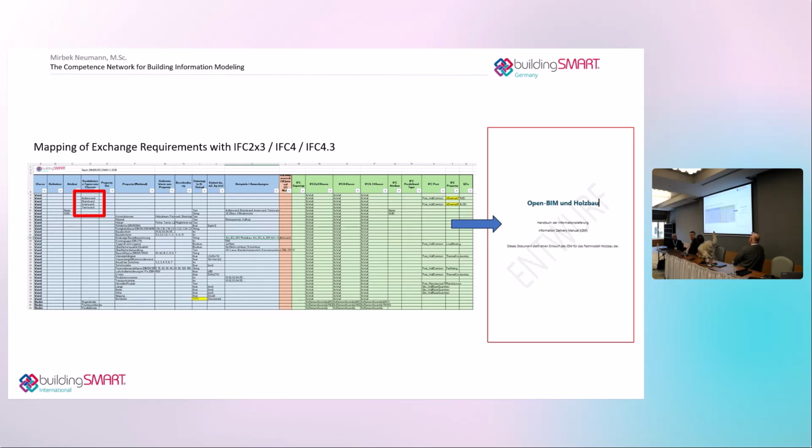We have identified many properties that are already covered by the IFC schema, just some attributes. There's a difference between attributes and properties, right? You know that. Name is an attribute, it's not a property. GUID is an attribute as a global identification, so you also have that. And so on, description. In some cases, of course, you need fire safety.